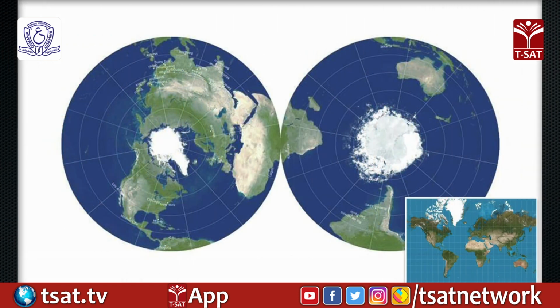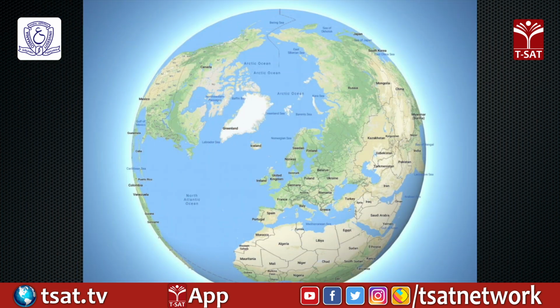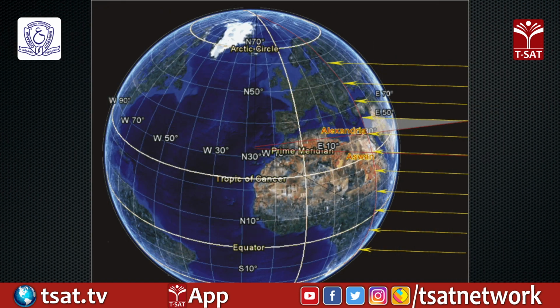There are some distinctive advantages in using map projection. First, a map projection allows us to use two-dimensional maps, either paper or digital, instead of a globe. Second, a map projection allows us to work with plane coordinates rather than longitude and latitude values. Computations with geographic coordinates are more complex and can yield less accurate distance measurements.